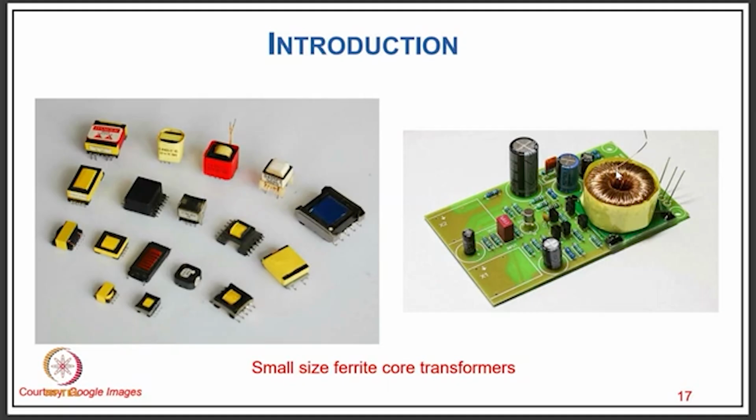I mean, new applications also emerge, like welding and others, even for many electronics equipment, as well as typically in case of your power electronics application for the purpose of isolation for gate drive and other applications. So there we are using this high frequency transformer for many purposes. One is the isolation, another is to get many output voltages so that we can convert into many DC